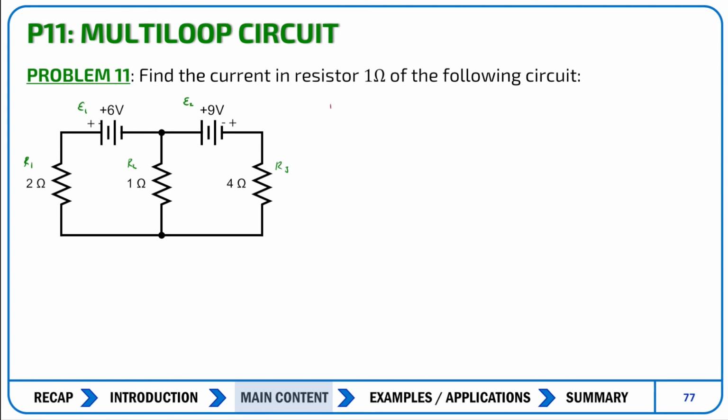So first, use Kirchhoff's rules. See what we can figure out. We're going to have to label the circuit with junctions and loops. So I'm going to use blue for my junctions. There's going to be one junction here, it's A, another junction here, which we'll call B. In terms of the loops, we're going to use purple.